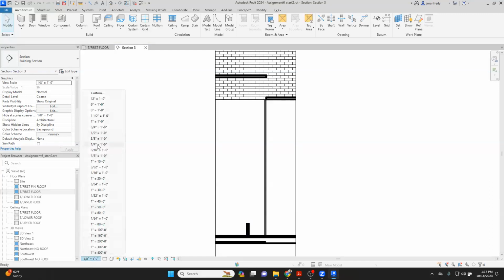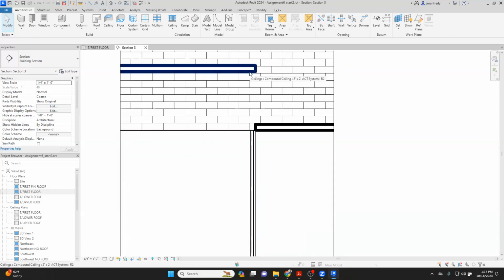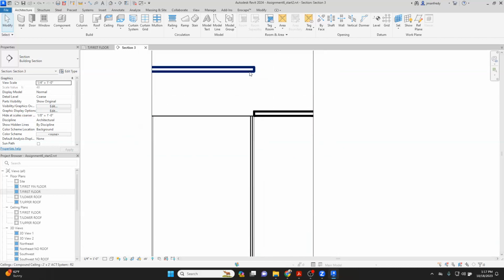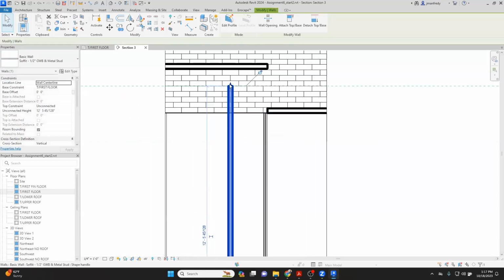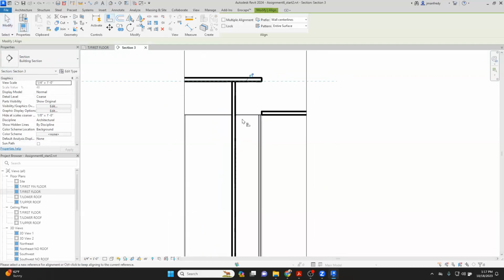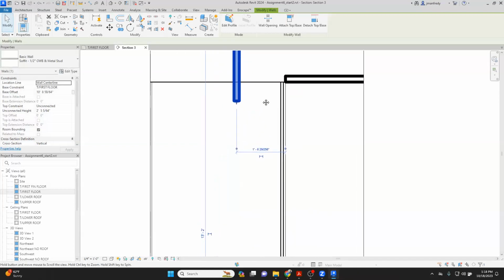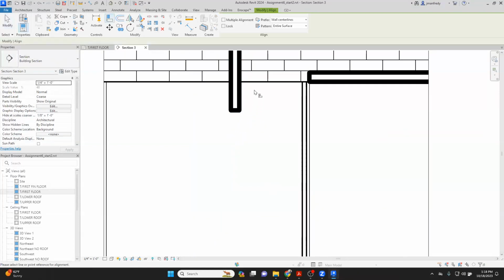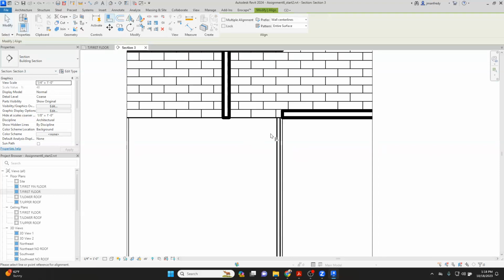Let me change the scale, make it a little bigger, 1/4 inch scale. The soffit needs to sit on top of this glass and go up at least to the bottom of the ceiling. And so I'm just going to basically stretch it so it runs into the ceiling. Just going to line it. And the bottom of it lines up with the top of the glass, which is aligning it up to here basically. And then I line it up left and right, right?